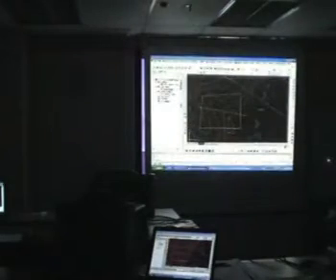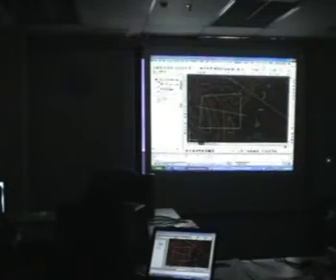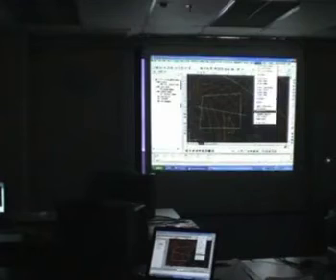So now we're going to run the volume calculations. In Land Desktop, we have 3 methods of volume calculations. One is the grid method, which is the normal manual method a lot of people use. They basically divide the drawing into grids, so the grid size, of course, is totally up to them. What they do is take the difference in elevation of each corner, take the average, multiply it by the area, and total everything up together. That's how we get the volume calculation using the grid method. Okay, that's the grid volume method.